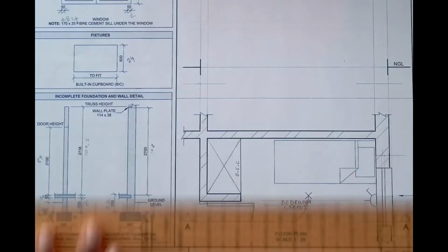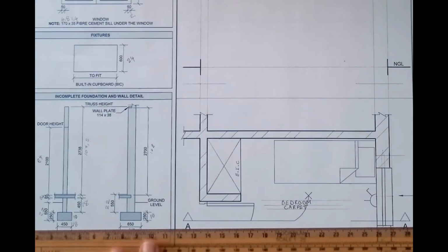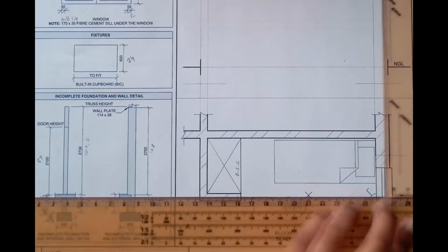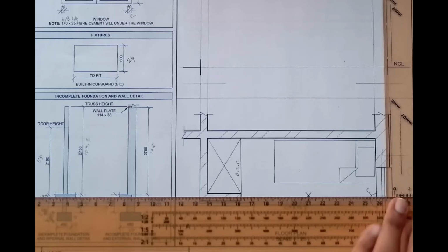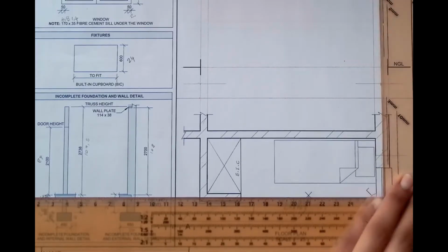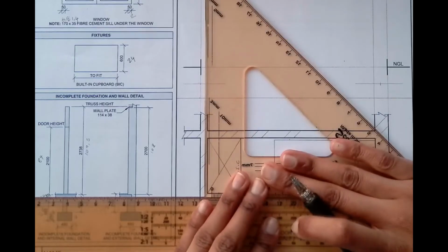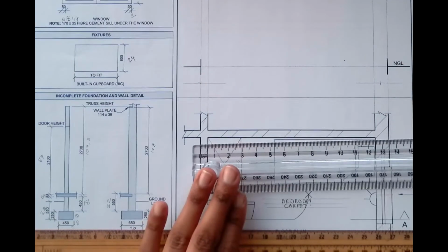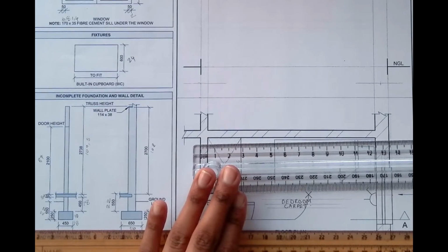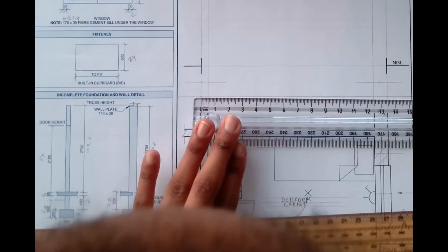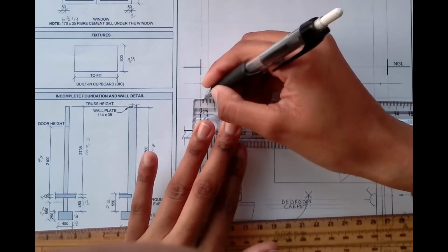And then the middle part, we already got it from the bottom, so I'm just going to project it from the bottom, which is there, and mark it. On this side we didn't get it, so I just need to measure the middle. I measure it here, which is 5, then 2,5 will be my middle point.